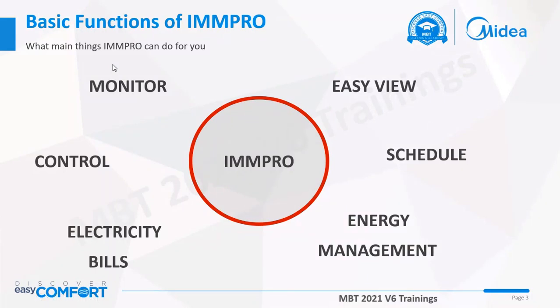And energy management. The energy management is just like we discussed in the central controllers, that the minimum cooling temperature limit or maximum heating temperature limit you can set from this one also. You can lock the remote controller, lock the wired controller, lock the fan speed, lock the mode. These kind of things can actually help in saving some energy. And for the outdoor unit side, you can start the auto energy saving mode or power saving mode. So what are these two functions? They are power management, energy saving.